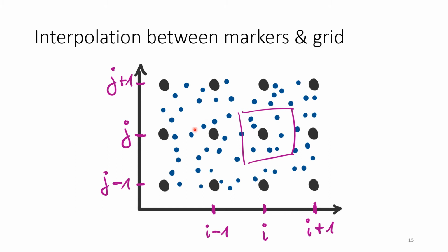For example, calculate diffusion, right? So some of the concentration has diffused, and then I would interpolate this diffused concentration back to each marker. Then I would calculate the flow, so the marker position would be updated based on my local flow velocity, and then I'm doing the next time step. Okay, and I have maybe a new marker distribution in my region of interest, and then I would again interpolate back and forth.